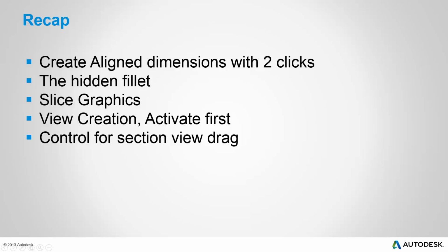The next thing we showed is a combination of slice graphics but also view options. So turning on slice graphics is a great way to be able to see down into your part when you're creating a sketch. The other thing though is oftentimes you may want to include geometry that would be removed with slice graphics, so turning on some of the different visual styles is a great way to have the best of both worlds.